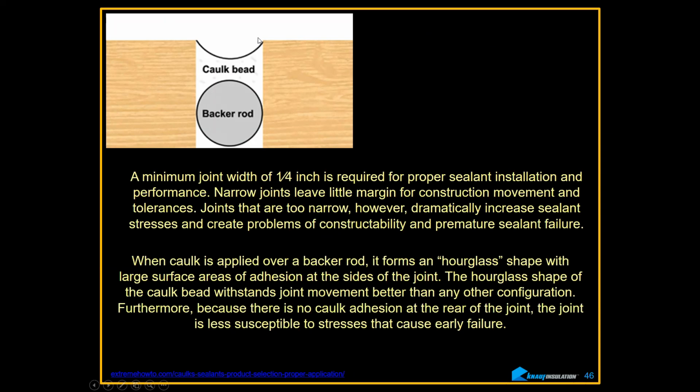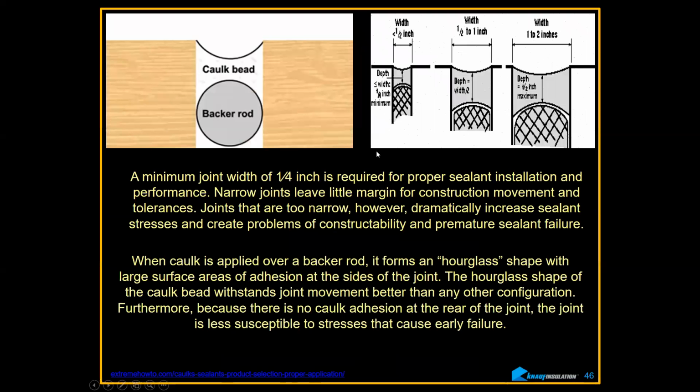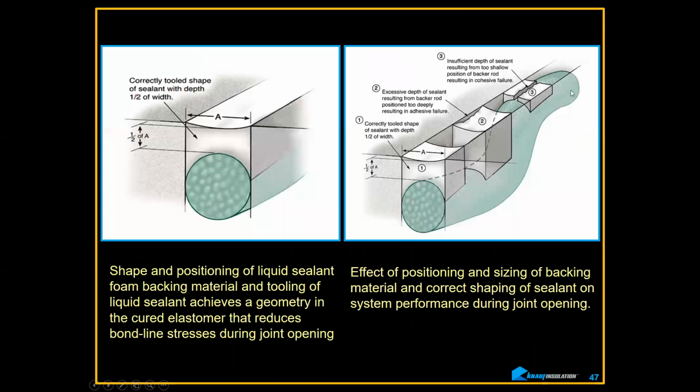Okay, you can find this anywhere you want on the internet. Okay, it's not made up stuff. And depending on the depth and the width, what you're going to have to do here depends on different widths and different depths. This is what happens if you're too shallow: there's not enough material here, it'll split and crack. If it's too deep, it's going to sag in here, and it's going to create an airspace in here that you don't want. This is what we're looking at.